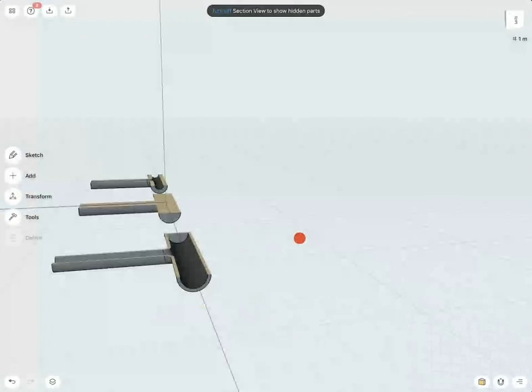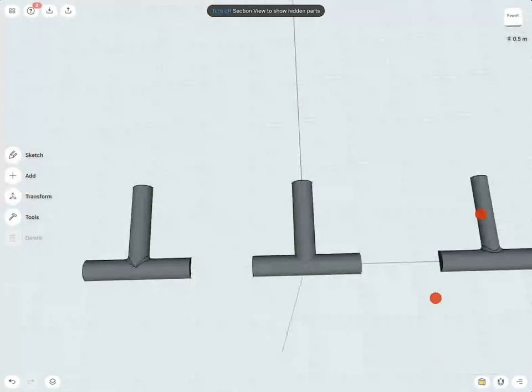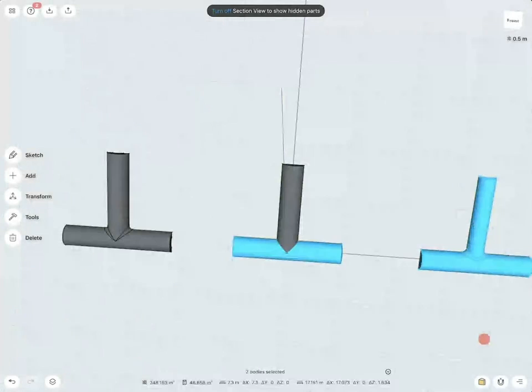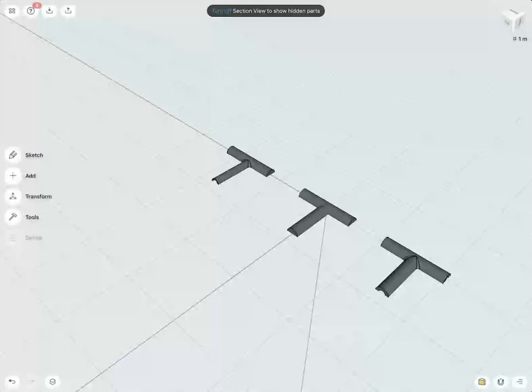So you see this is a little bit easier also to fabricate, because you need to keep in mind to insert this pipe into this pipe. On this pipe, I have to drill a hole where this one goes in and then also file the intersection correctly. This here is a little bit easier. I just drill my hole and then put this pipe in and then I weld it. So that's a quick exercise in how you can do those T-sections.